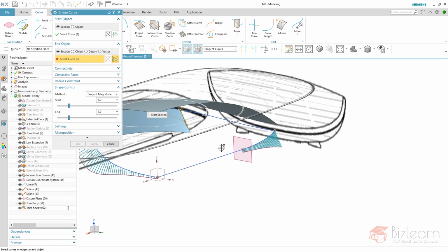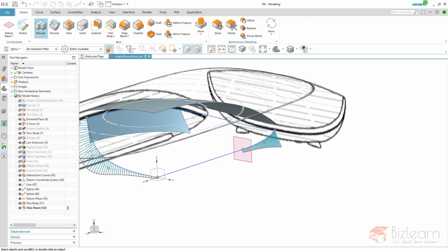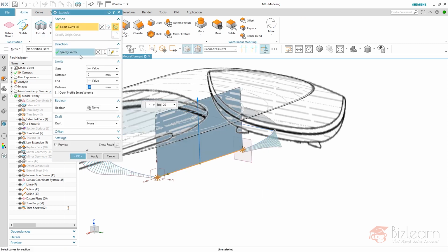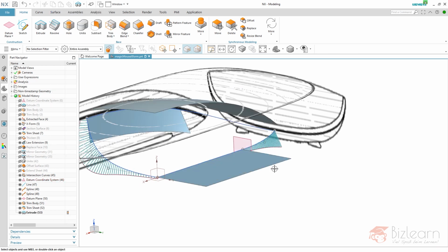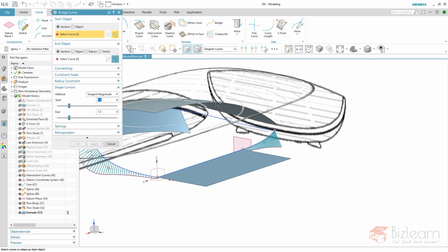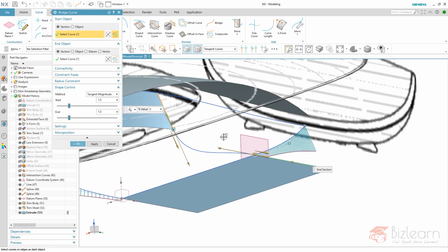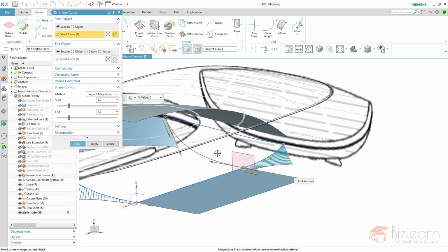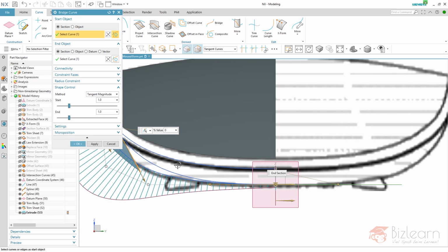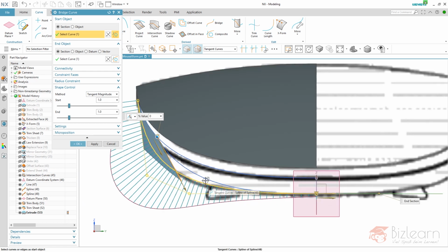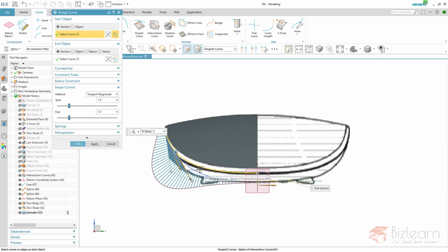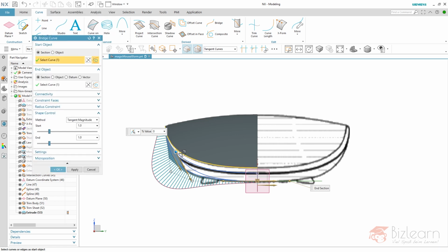Well, there's something I forgot, I guess. I'm going to just extrude this curve, and of course into Y, because I need this edge here. And I'm going to restart my bridge curve again. I need this one and this one. So what you got to do here is just reverse once. And if I compare my splines now, you can see it seems to be fine. I think it might be satisfying somehow, but I really want to make sure that the poles are scaled proper.